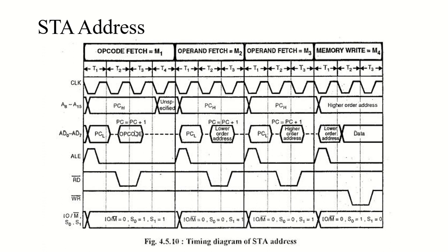But the interesting thing is, the address will have a total of how many digits? 4 digits. How many digits can H and L point out? Only 2. So my address consists of a total of 4 numbers, and H and L can only point to 2. So what about the remaining 2 numbers? For that we are using the memory read cycle one more time.